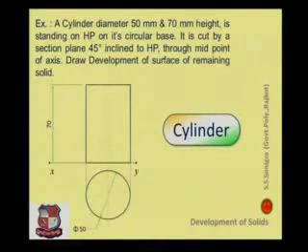Many students skip to locate various types of lines. Here, this middle one should be drawn as a center line. Here dimensions should be inserted by any single dimensioning method. Suppose I have inserted a dimension with the align method, then throughout this drawing you should go through the similar dimensioning method. Say here 70 mm with a similar method. You cannot use the unidirectional method over here and the align method over here.